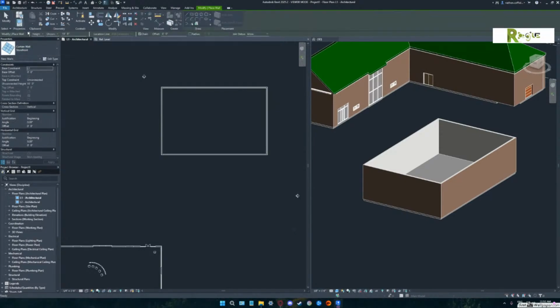So when you do just a normal architectural wall and it says height, you can say unconnected, and most of the interior walls would be unconnected and 10 feet high. The stuff inside there would go up to the ceiling. Okay, so what part is confusing you about the L1 and L2? If you said L1 and tried to draw a wall, you would be drawing a wall that goes from L1 to L1. So in other words, it's 0 height. Whereas when you say L2, you're going to the floor above.